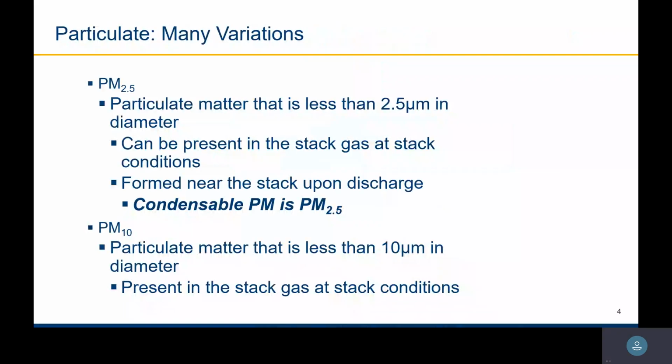So the two categories of particulate matter that you most often see referred to are PM 2.5 and PM 10. It was always PM 10 originally, and then more recently it's been moved to a PM 2.5 limit. 2.5 is particles that are less than 2.5 microns. What's important about that is those are the ones that can do a lot of damage when they get very far down into the lungs, and they can also get into the bloodstream. The larger PM10 particles may cause people with asthma to have trouble, but they're typically something the lungs can handle. They really can't handle the 2.5 very well. So most of the newer regulations are geared around the PM 2.5.